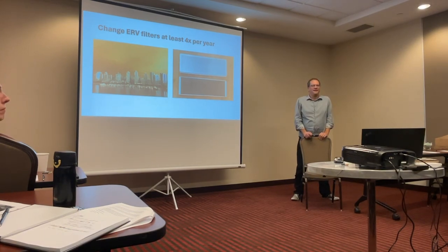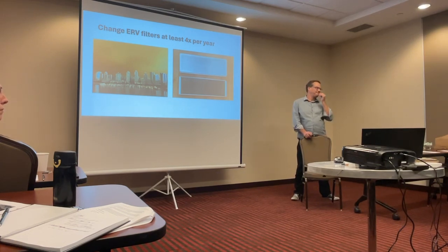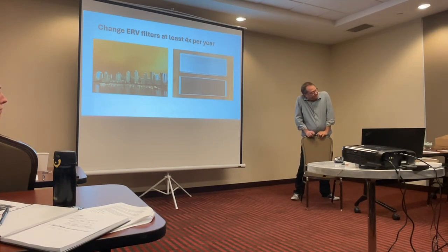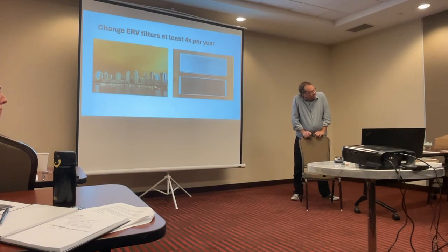I was thinking in series, I guess, with the HEPA filter. So what we do, we had 500 parts per million in Portland during wildfires, is we rely on a MERV 13 filter on the HRV, then we run inside the house a separate big room-size unit that has both activated charcoal, which is cheap, and a HEPA filter. So that can bolster it, but only during those smoke events. The rest of the time it goes up and down.